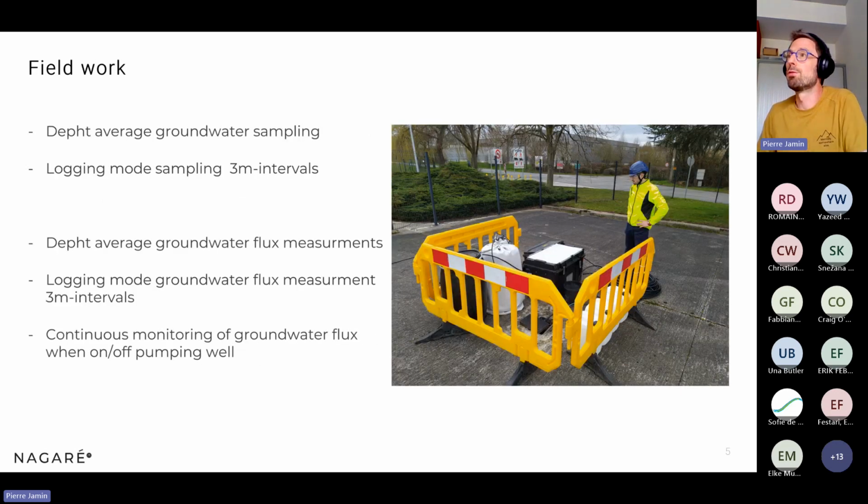So in the field, we performed the classical groundwater sampling. We did the sampling, depth average, on two monitoring wells around the pumping well and also at the pumping well, and we also performed groundwater flux measurement on the two monitoring wells to better quantify the flux around the well.